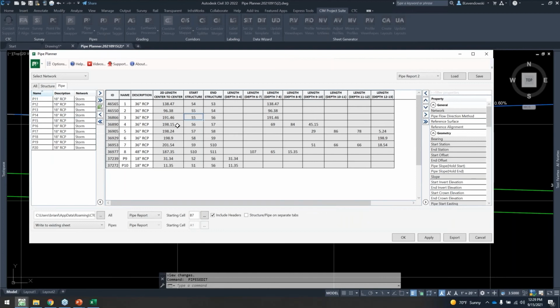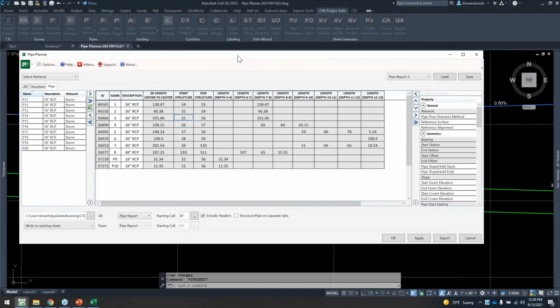I have seen people starting to use our auto grader tool for building out some trench calculations. If you're not familiar with this, this is feature line automation. Takes your standard feature lines. You can do simple things like daylighting to a surface, right? So you'd have some kind of feature line at the bottom of your pipe. You could offset a couple of units left and right and then target up to your surface to generate those trench quantities.